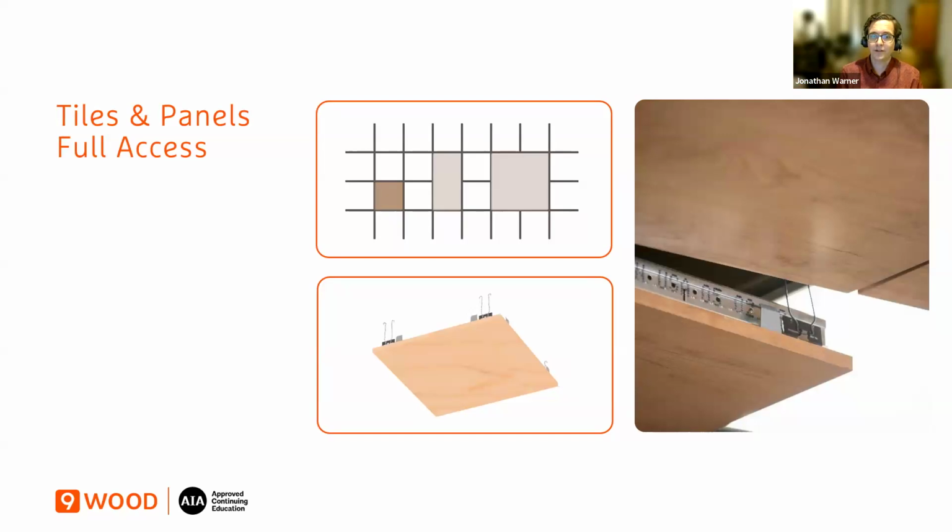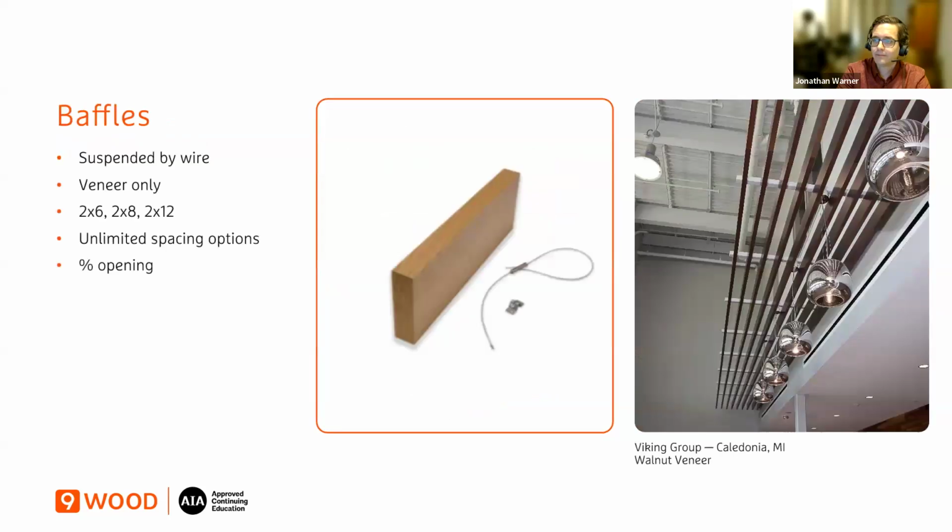A full access system is going to be more expensive. And so it needs to be easy for the maintenance department to use, and maintain consistent reveals even after years of access, right? So it doesn't look funky and dissatisfies the client over time. And so just check with your manufacturer, find out what choices they have. But those are things to watch out for.